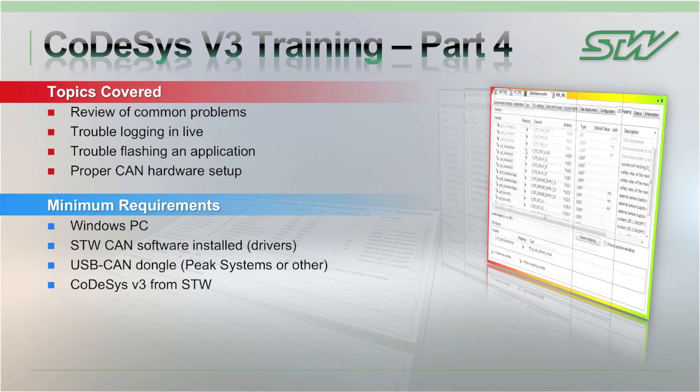This fourth video is going to cover some common problems that you might run into while working with CoDeSys or trying to flash or log into your controller. One of the first things we'll talk about is trouble communicating with the gateway when you're trying to set the program up to log in.